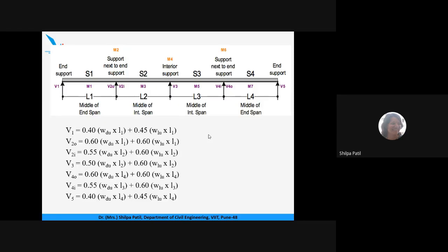Okay. And when we calculate the span moment, for this span moment, we normally calculate the area of steel. And for the support moment also, we need to find out the additional area. But how to find that, I will explain to you. But if these spans are the same, then there will be no problem.